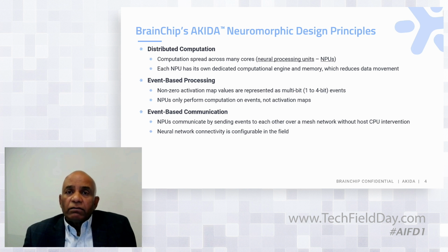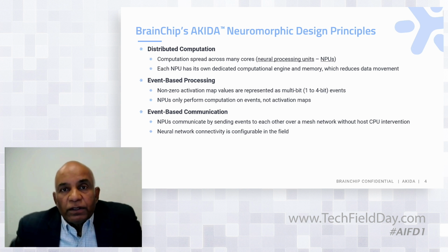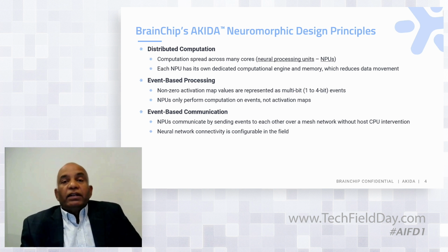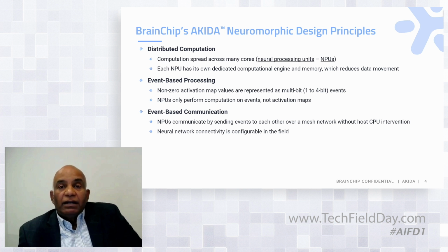And the actual network that runs on the hardware is configurable at run time. So today you could be running an audio network on the same hardware, and later a vision network, or a LiDAR network, or a smell or somatosensory network. For all of those, the configuration of the connectivity between neurons is changed. You load the weights and you run that. So it's really the configuration of the network you run. It's really a processor. It's not designed for a specific network. It's designed to process neural computation, and which network you run on it is configured.